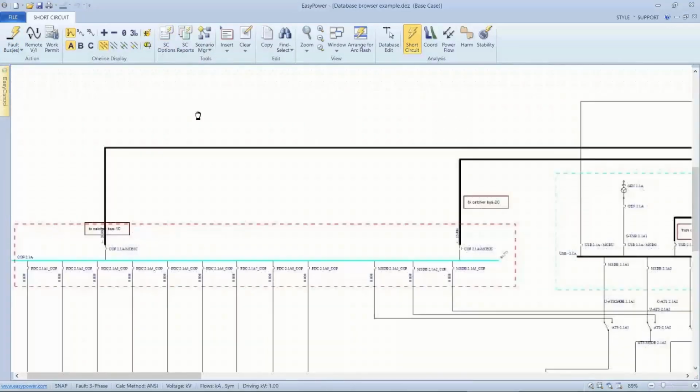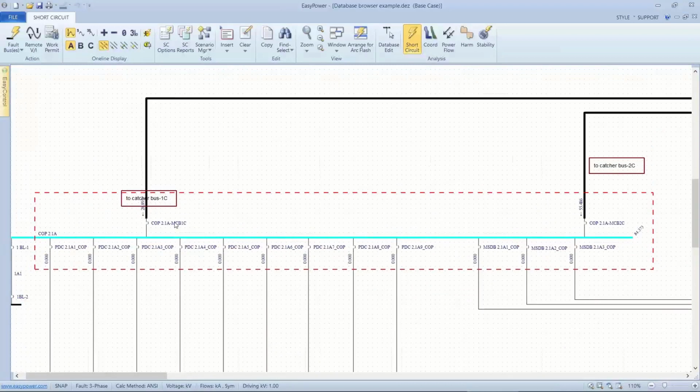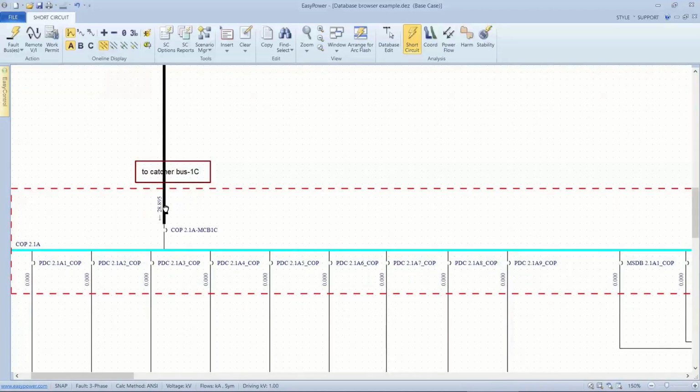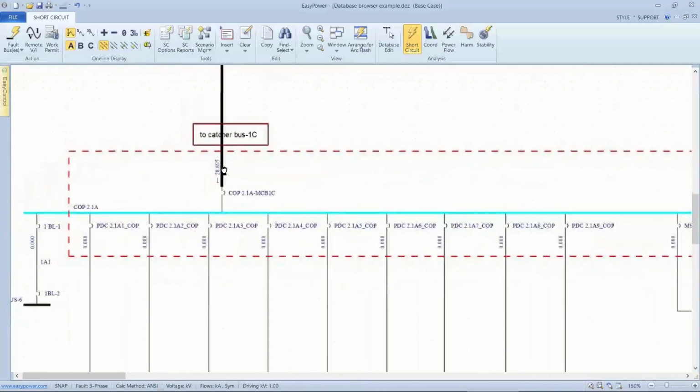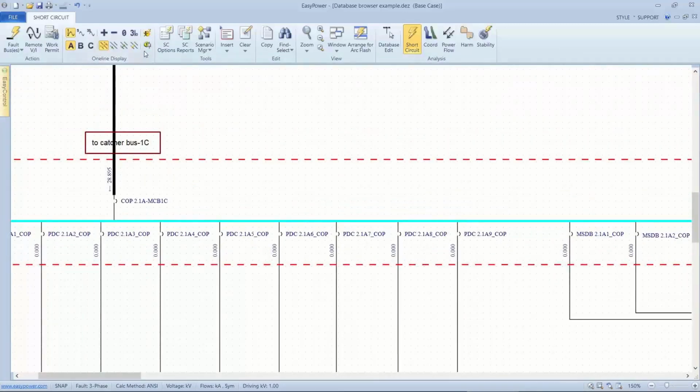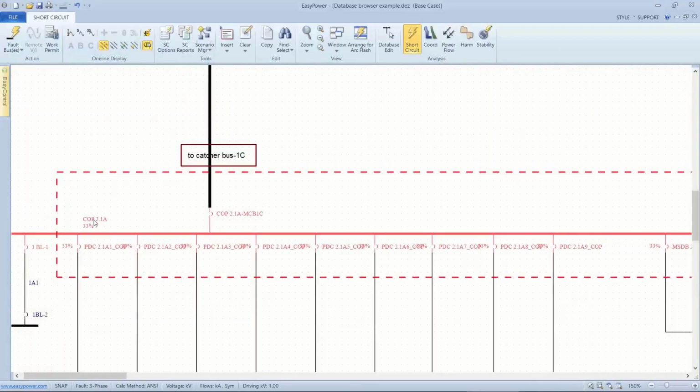So by faulting, this is going to show me the current on this particular bus if it has a 3-phase bolted fault. And what I see is 28,000 some odd amps coming from upstream and nothing because we have no loads downstream. And the question is, will that 28,000 exceed the rating for the bus or the elements on there? Now these are the answers, yes.